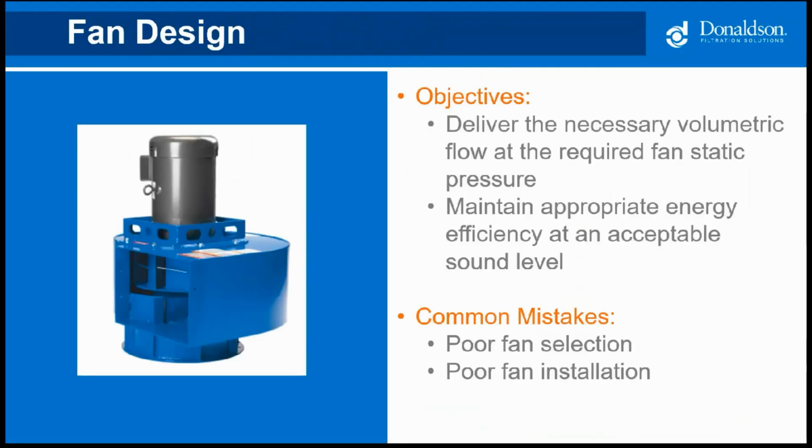So it has two job responsibilities. First, a fan must deliver the necessary volumetric flow at the required static pressure to drive the operation of the system. And since many dust collectors can operate with dirty and clean filters, the required airflow often has to be maintained over a range of static pressures. Secondly, the fan you select should be able to deliver the desired static and airflow with an acceptable energy efficiency at an acceptable sound level.